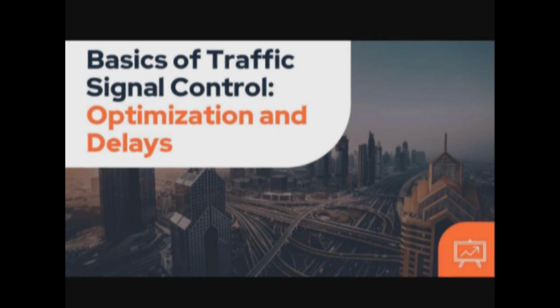Basics of traffic signal controls, optimization and delays. Traffic signals work on the basis of allocating separate time periods to conflicting traffic movements at a highway intersection so that the available carriageway space is utilized as efficiently and safely as possible. Priority can be varied with the time through the cycle of the signals. Within urban areas in particular, in situations where a road has a number of intersections along its entire length, signal linking can be used as a method for allowing almost continuous progression of traffic through the route.